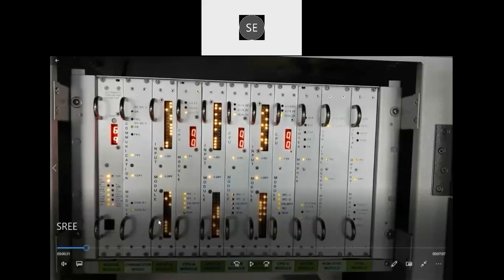So this is the power supply CPU module. As I said, there is a provision for internal health check of the power supply. Here, if it falls below 4.5 volts, this LED glows. If it is more than 5.3, it is close. So we have to maintain the supply between 4.5 and 5.3 volts for trouble-free operation of the system.